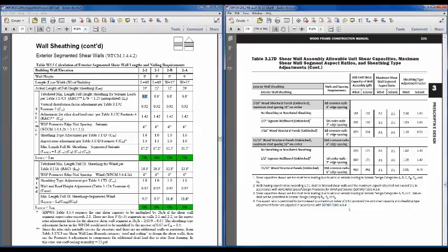And I'm not going to jump there because it'll take too much time to go there. But if you were to go there, you'd see that there's an adjustment factor. And I'll come back here to the workbook now and take a look at this first footnote in the workbook that I've highlighted here below, because that gives you the explanation. If you were to go to table 4.3.4 it allows you to take a 2B/H adjustment to your capacity. Well, since we're dealing with shear wall lengths in this table, we're using the capacities that are spelled out in the table to calculate a shear wall length.